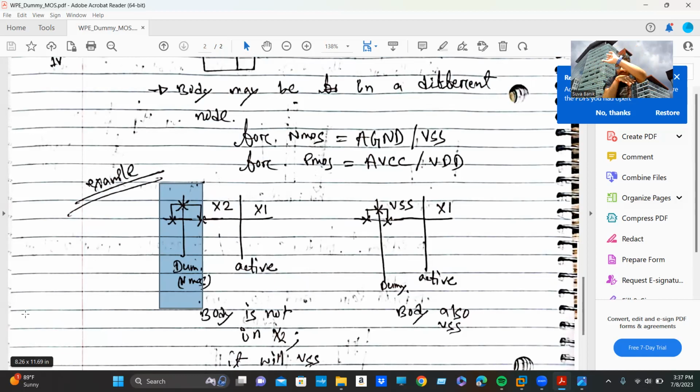We can connect this whole transistor to VDD or VSS, meaning drain, gate, body, source, as well as the fourth terminal of the transistor are connected at the same potential. There is an option in simulation or in LVS that we can pass LVS this way, or the tools basically think that it is a dummy. It's a different issue. I will show it in my real-life example when I show Cadence. But right now, let's try to understand the left and right corner transistors, how to do that.